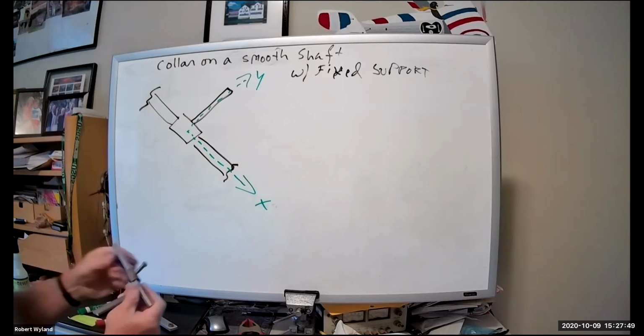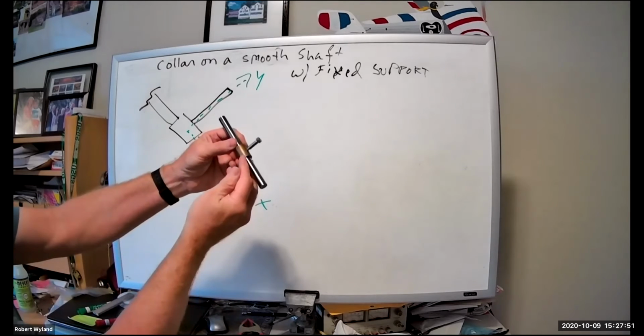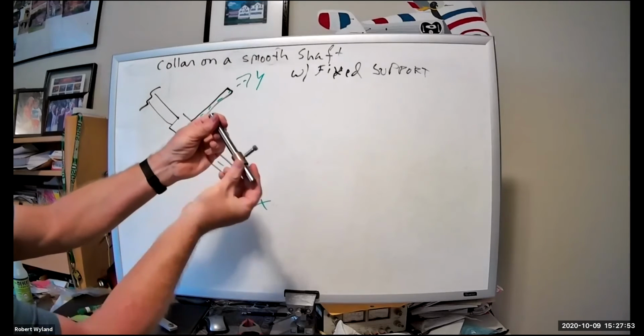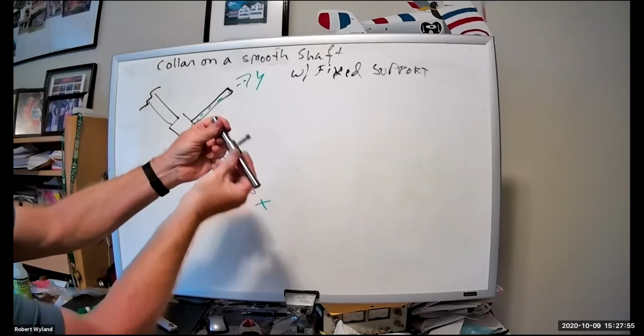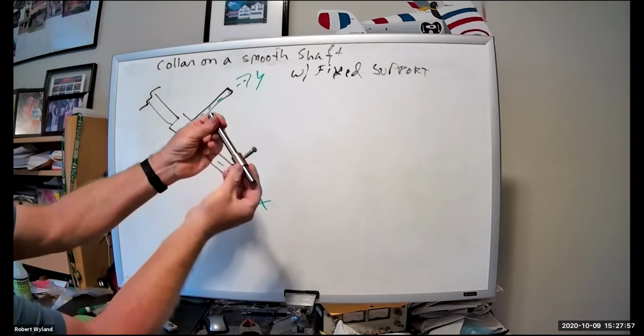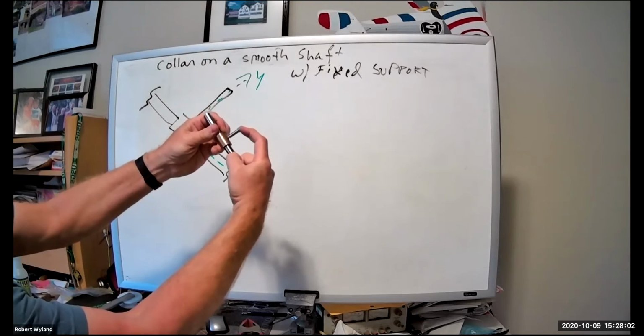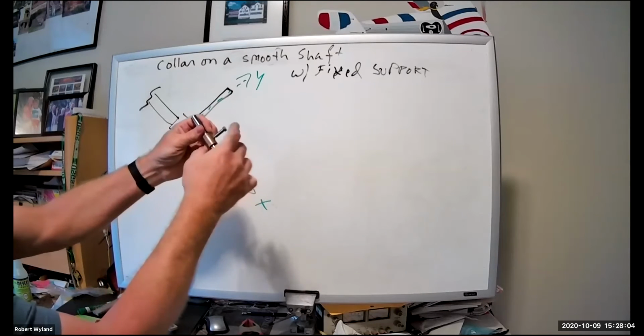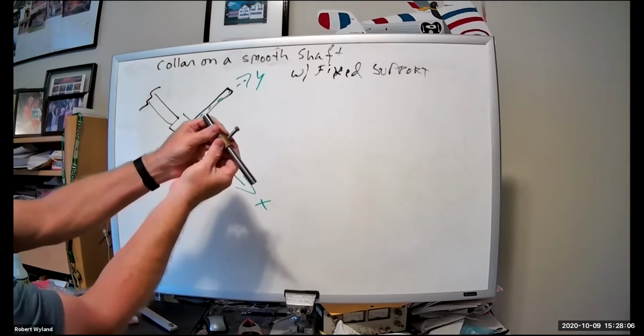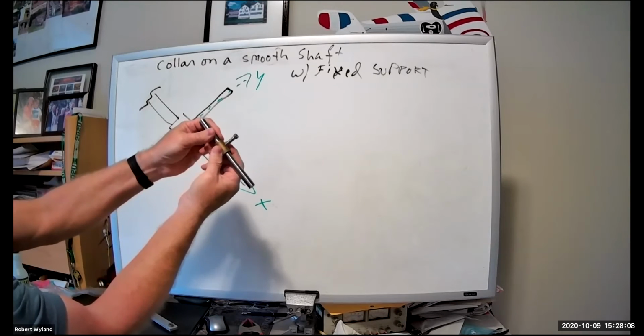So now when we go back and we look at this, when we talk about pushing in X, it slides and so it moves. So we have no reaction. There's no force resisting along the X direction. And if I'm pushing in the Y, there is resistance. And if I try and rotate this thing about Z, it doesn't want to rotate.